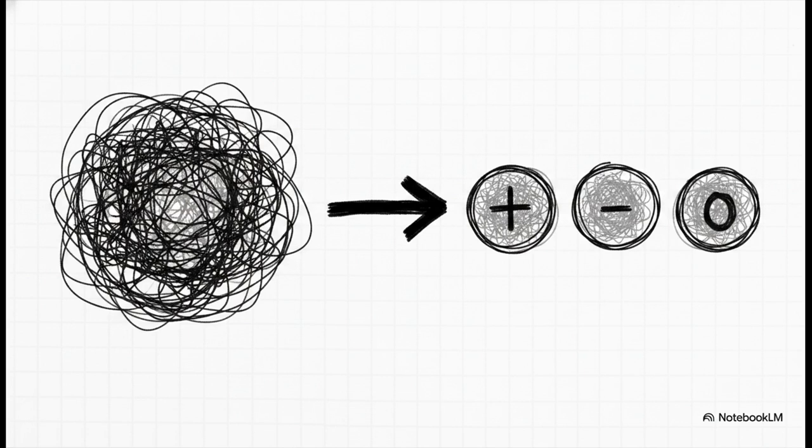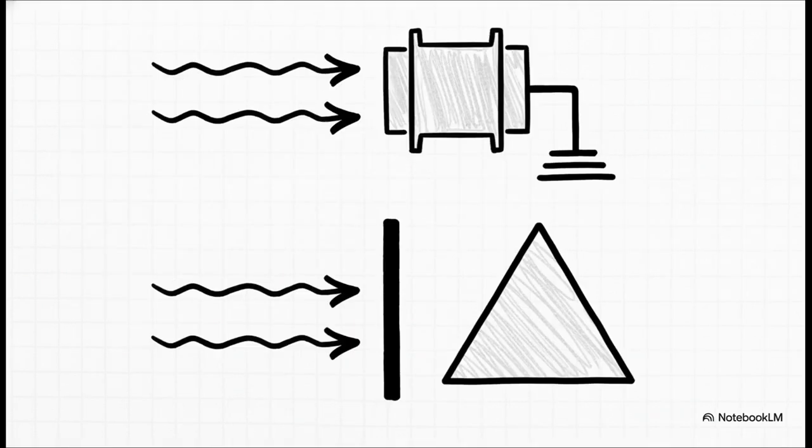You solve each one independently using the exact tools we just learned and then combine them based on the specific type of fault. Now, zero-sequence networks need some special attention. Unlike the positive and negative sequences, all 3 zero-sequence phasors are completely in phase with one another. Because of this, zero-sequence current absolutely requires a physical return path to ground or a neutral to flow. It'll flow easily through grounded transformer windings, but, and this is key, it is completely blocked by ungrounded delta windings.